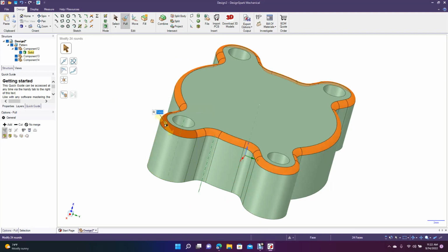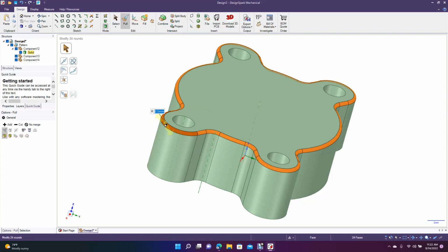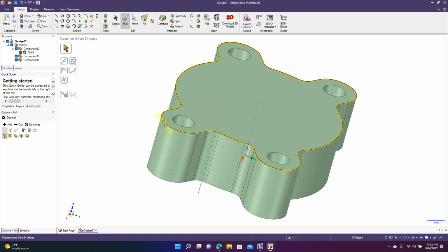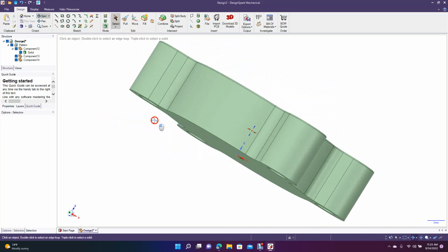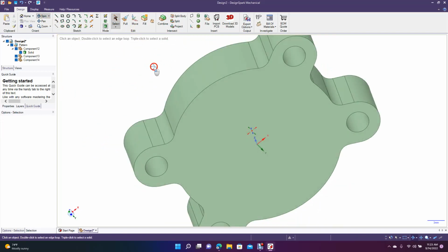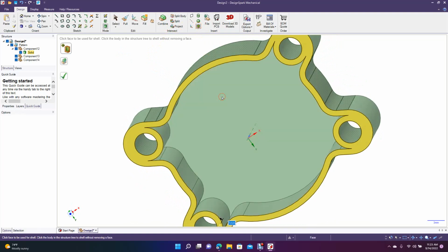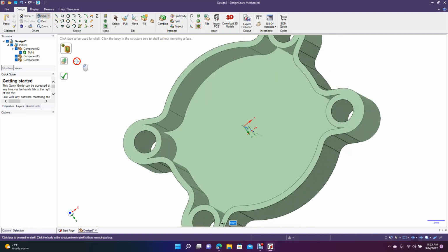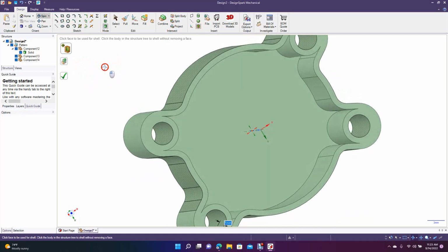We're going to add a 1 millimeter fillet. Actually, that's too much. Let's do 0.5. No, that's too much too. I don't like that. Let's do 0.2. Okay, that's a little bit subtler. All right, so 0.2 fillet on the outside. And then we're going to go ahead and shell this. So we'll go get shell. Click there, 1 millimeter. Let's spin this. Decent little part there.